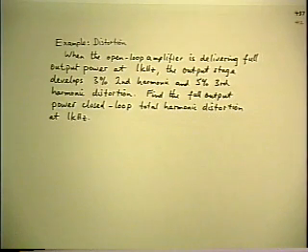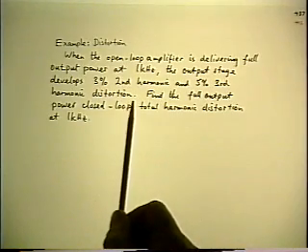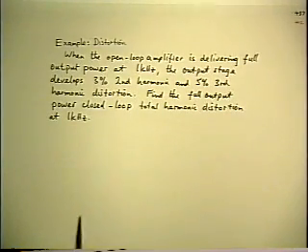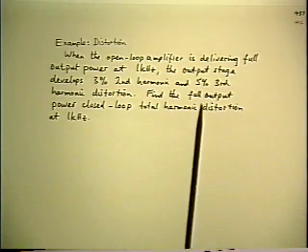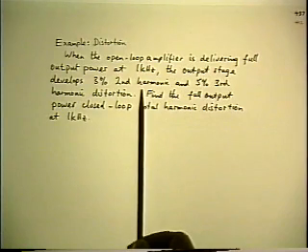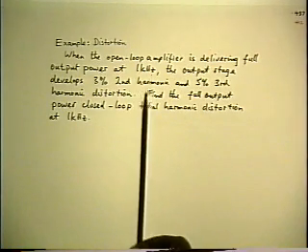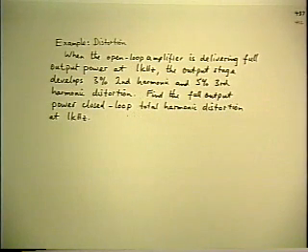The only thing to find out is, if this is what it develops, measured open loop, what do you get in the presence of the closed loop feedback? You have to compare the same reference condition. That is, you have to compare the condition when the output is still being driven to the full level, the same level at which you measure the open loop distortion. That's the only way you get the same distortion generation, and then you find out how much the feedback reduces it.